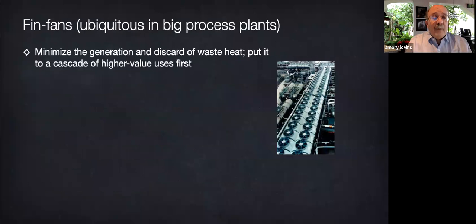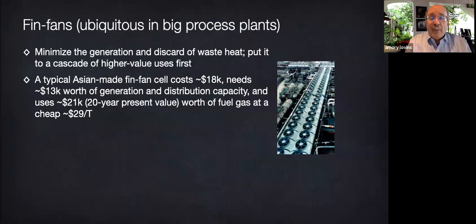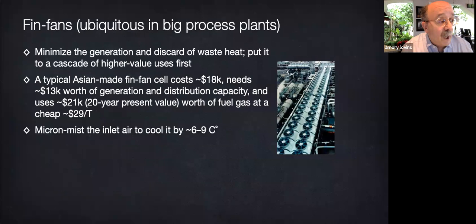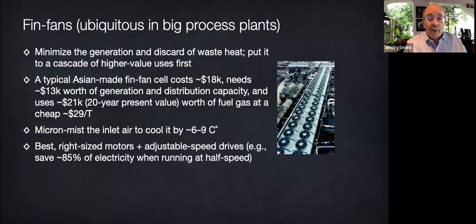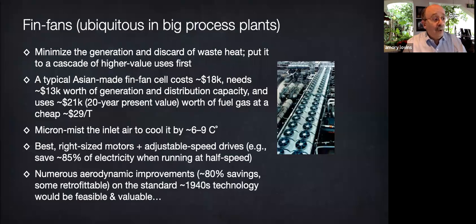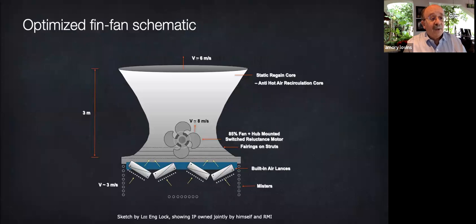After minimizing the heat to be rejected, we would scrap the existing fin fans, which are 2/3 of a century old designs. We put in redesigned ones, micron misted on the inlet, get it a little cooler with very efficient motors and adjustable speed drives, and above all, with aerodynamics much better than the standard 1940s design antiques we saw, which are standard in the industry. So the new design would apply basic physics like this.